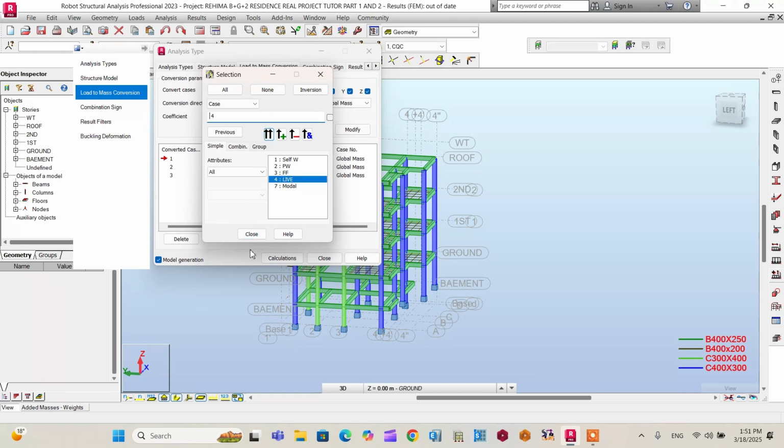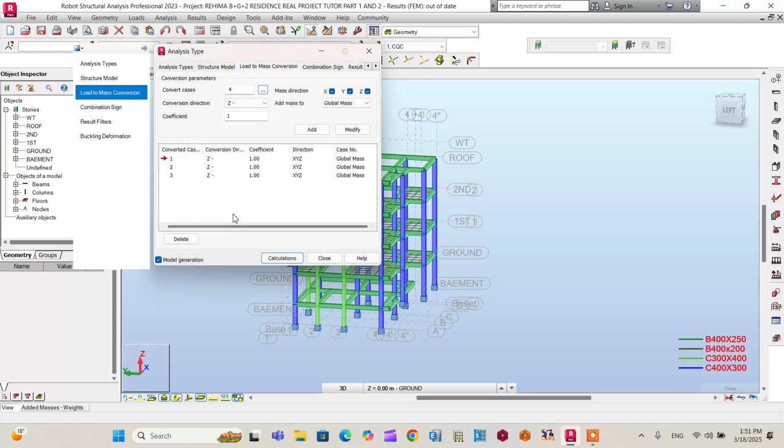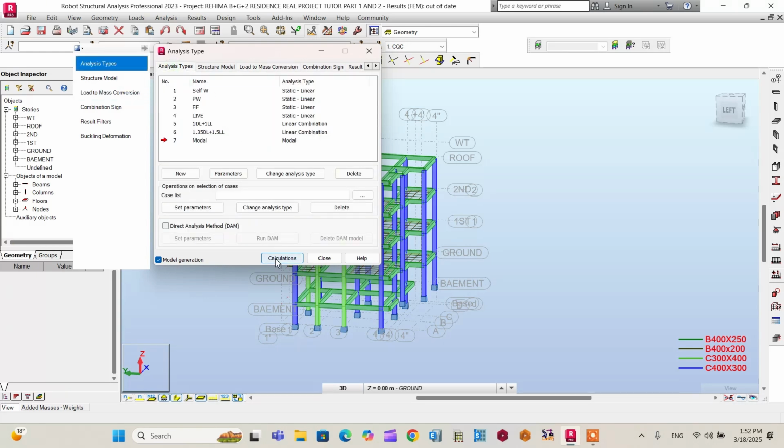I will tell you some pointers here. For live load, the coefficient is changed. This is because in case of a live load, you can use 30%, that is 0.3. After that, you have to reduce it within 20%, so I have to use 30% times 0.8. So the value is 0.24. The software calculates it itself. Make it add. If you have any question regarding the detailed calculations in our tutorial, you can ask in the comment section. After defining all this, let's proceed to the calculation.